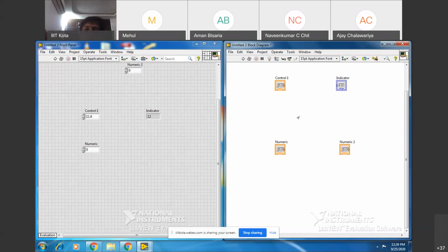So Control B, you have to be careful, because sometimes one connection is wrong. Since the system is interconnected, the wrong will be propagated backward also. It may highlight many wrong connections. So if you use Control plus B, that time it will clear all the wrong connections. So you will have to reconnect again.